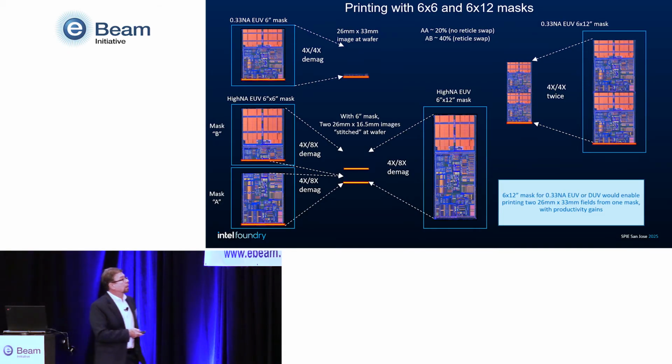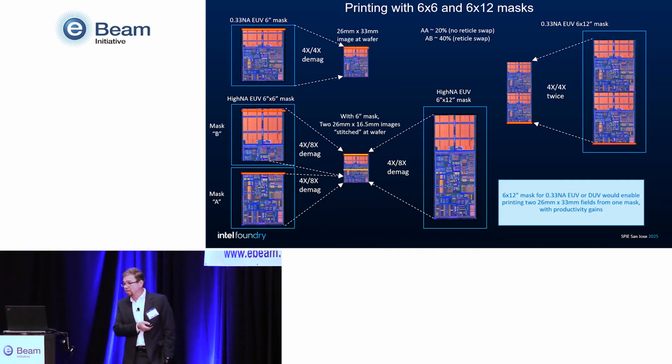So a normal exposure, you have 1-to-1. And today, we have the first mask, and then the second mask. And of course, I want to point out this no-fly zone. You cannot put critical dimension features in that butting area.